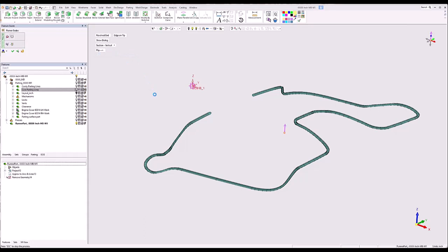Now the failure originally, sometimes the geometry of that curve, there's something about it. By going into wireframe approximate to arcs and lines, it simplifies or cleans up that curve. And now going into the runner command, I get a result that's a lot better, a lot cleaner than previously.